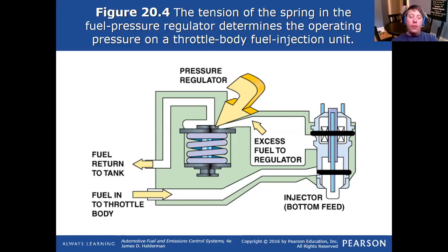On your more advanced fuel injection systems that are pulse width modulated, where we are supplying fuel pressure and fuel volume on demand by cranking the speed up or down on the pump, there typically will be a rail pressure sensor for feedback, so the computer technically knows what the fuel pressure is. That's assuming that the sensor on the rail is delivering correct information, which is a whole world of other problems and other discussions if that goes bad that we'll talk about.